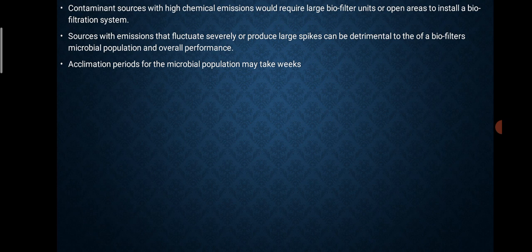Acclimation periods for the microbial population may take weeks. Sources with emission that fluctuate severely or produce large spikes can be detrimental to the biofilter microbial population and its overall performance.